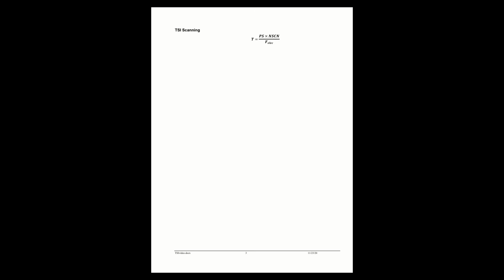Well, so let's look at an example. As I said earlier, I tried to set the frequency of the reference as high as possible so we could lower the scan time. Well, with that setting, I'm getting about 4 milliseconds per scan when it's touched. Okay, and so this is a touch time, which is the worst case, right?